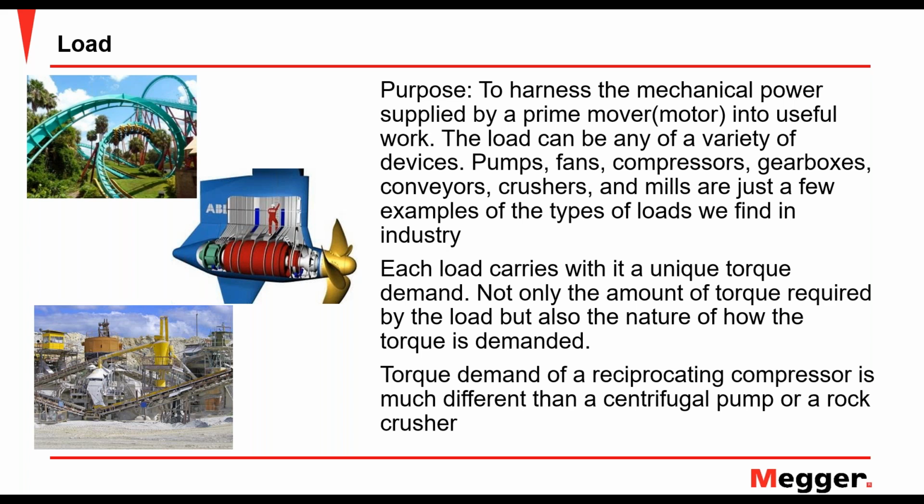The torque demanded by a reciprocating compressor is much different than that of a centrifugal pump or a rock crusher. And the torque demand there is something we're going to give you with the EXP or dynamics testing in the form of a torque ripple or instantaneous torque. And that draws us a picture of what that motor is seeing through the air gap of that load.